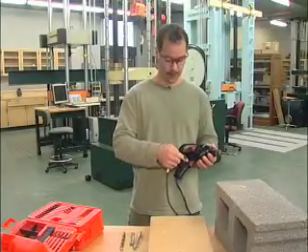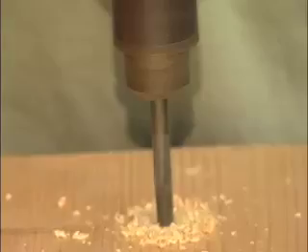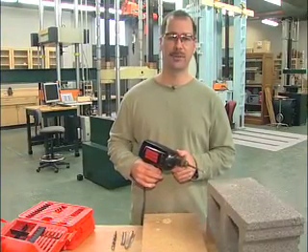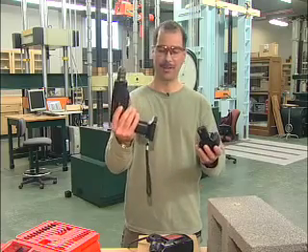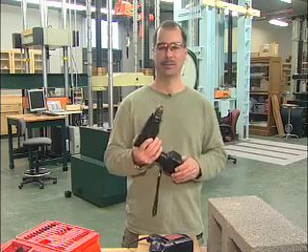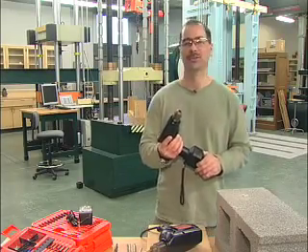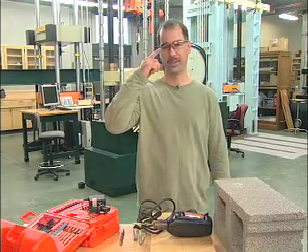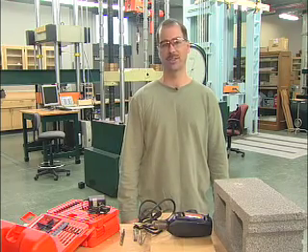Keep your hand away from the trigger when tightening the drill bit in place. Many fingers have been damaged this way. Even drilling wood can heat up the drill bit, so let it cool before removing it. If you like the mobility of a battery-operated drill, the better the battery, the longer it will operate. But that may mean a bigger battery that's heavier to lug around, so make sure it's fully charged before using it. And finally, always wear your safety glasses. A tiny piece of debris will feel like a boulder if it gets caught in your eye.